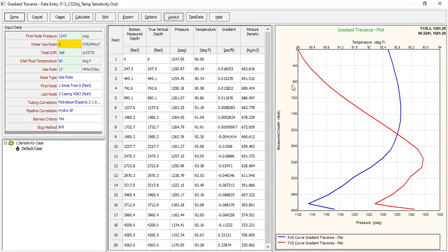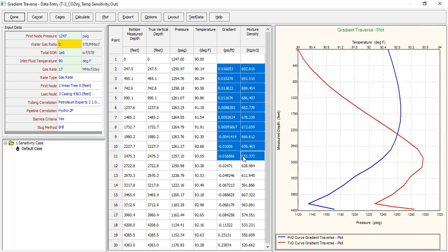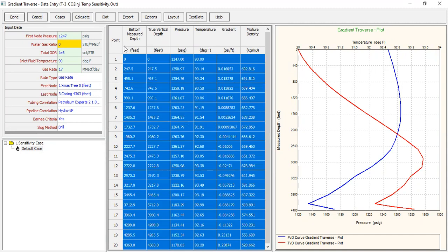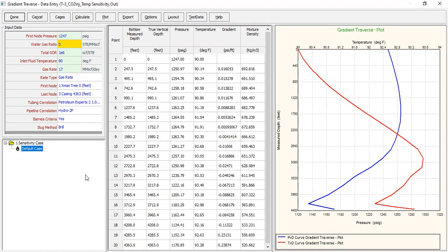Okay, so here although the gradient shows very small, it's because you will still suffer friction pressure that is quite high, so it will cut the gradient. Although you have a high hydrostatic gradient due to liquid phase, the friction pressure decreases the final gradient. But based on the mixture density, the phase is quite heavy. And if you check the phase diagram, it's safe.